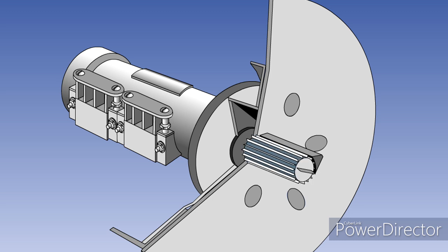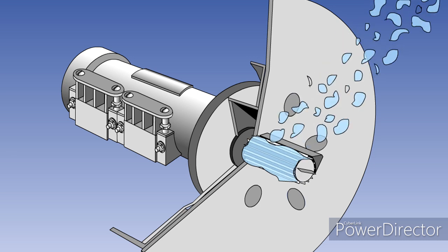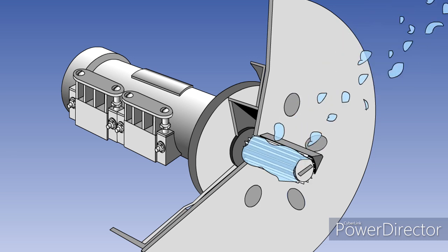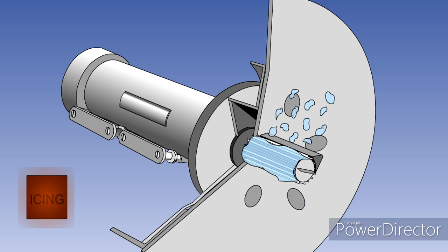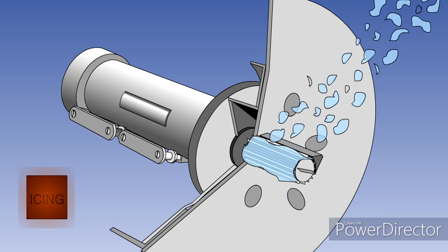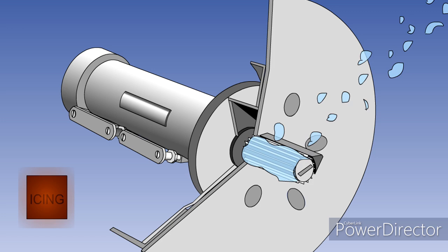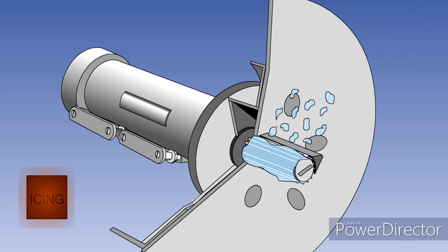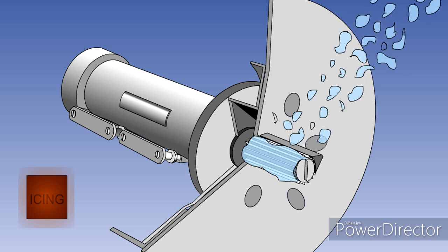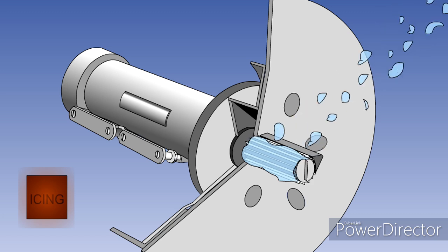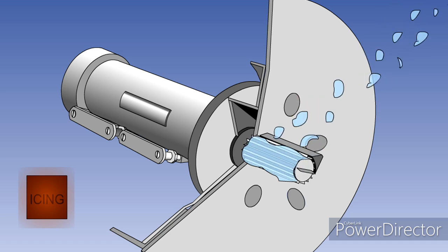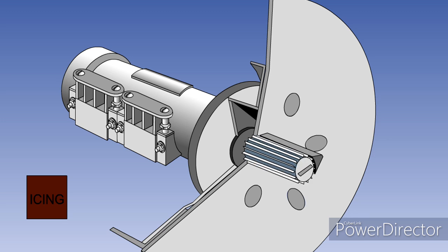Under normal conditions, little torque is required to drive the rotor. In icing conditions, ice builds up on the rotor and is shaved off by the cutter. Shaving off the ice requires greater rotational torque and causes the motor to rotate slightly in its flexible mountings. This movement operates a micro switch which gives an ice warning. The warning remains as long as ice continues to foul the cutter blade.